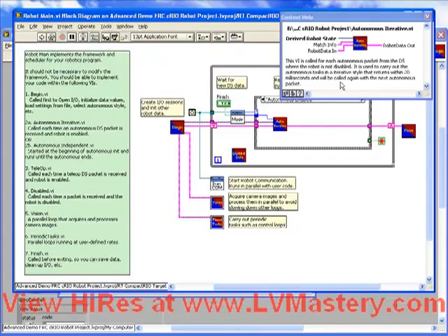It's important to understand the difference. From the point of view of the Robot Main.vi, the iterative mode is like a process you have to look at every 20 milliseconds. You have to look at it, make all the calculations, and spit it out again. Whereas the autonomous independent VI, it's like a process that you spawn. You tell it to start, you give it the data it needs, and then you forget about it until it's finished. There are advantages to both. My personal recommendation is that you use the autonomous independent VI, unless you're a very advanced LabVIEW programmer.